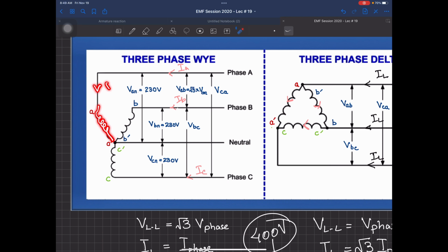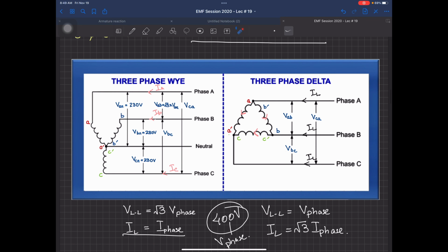So what is the phase current flowing over here? That is IP. What is the phase voltage over here? That is V phase. So the power for a three-phase circuit will be equal to V phase multiplied by I phase and multiplied by cos of theta. Why cos of theta? Because you have to take the power factor into consideration, and multiply this all by 3, because there are three phases and they all are taking the same magnitude.